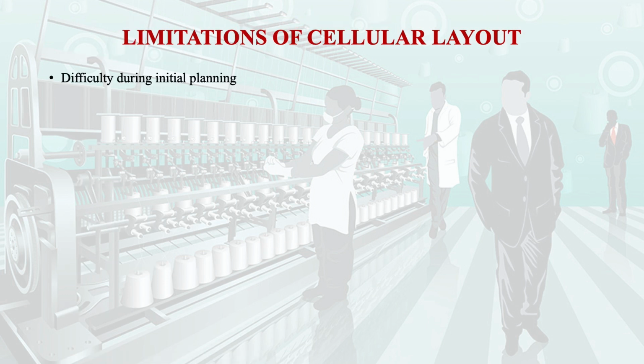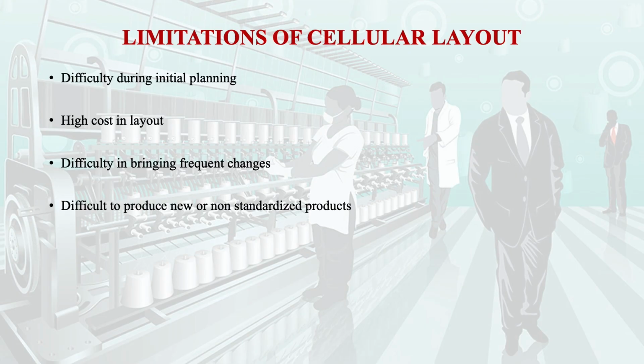The limitation is initial planning. There is an involvement of high cost, and if there is a change, it is very difficult to change the group technology or the cellular layout. Even if we are focusing on a certain family, and if a non-standardized product comes, it is very difficult to go for a new product or a non-standardized product.